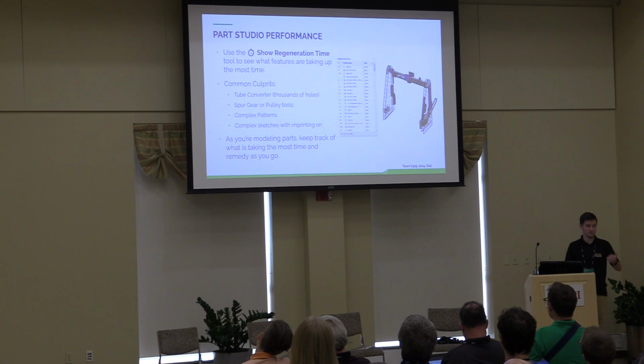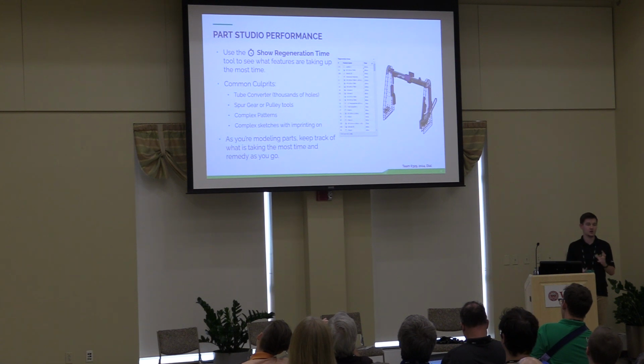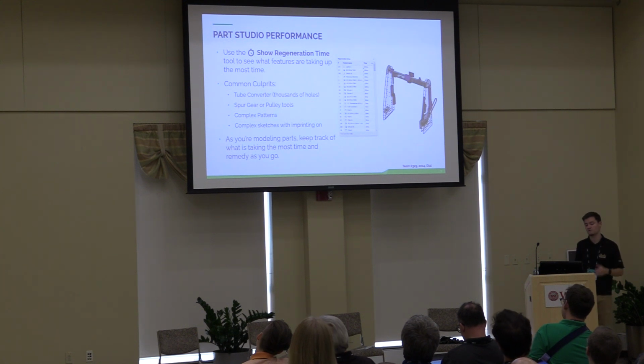Things like adding in spur gears or pulleys that you're then going to further modify, that's a common one because again, spur gears, pulleys, a lot of complex geometry, lots of splines on the bottom of the teeth, any type of complex patterns and complex sketches that you're doing on different faces with imprinting on. As the imprinting gets brought into your current sketch, that can also cause some slowdowns.